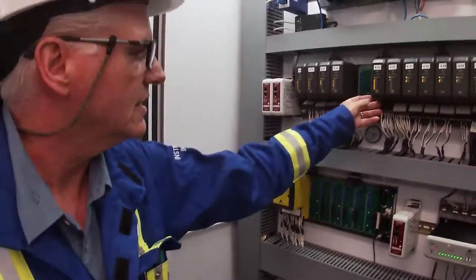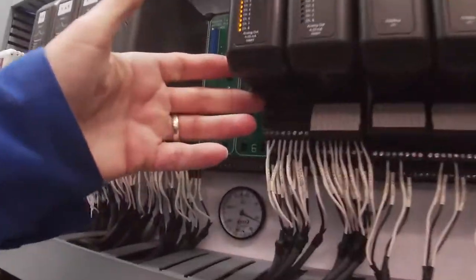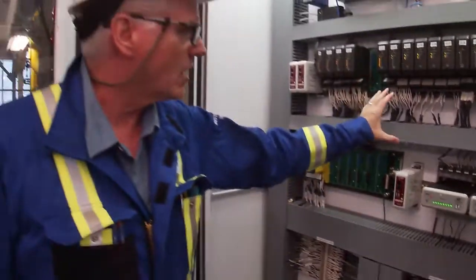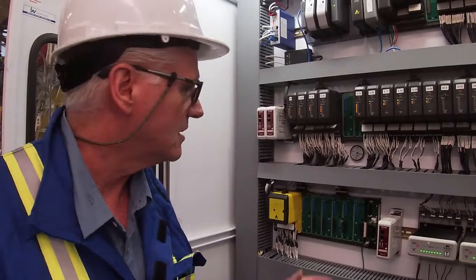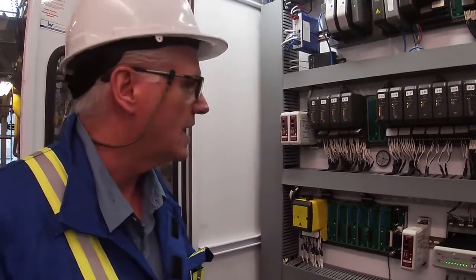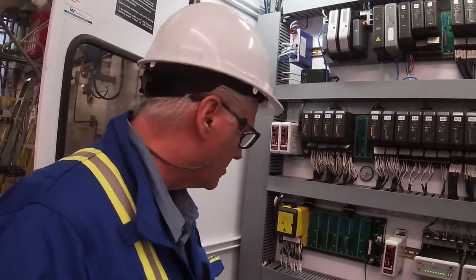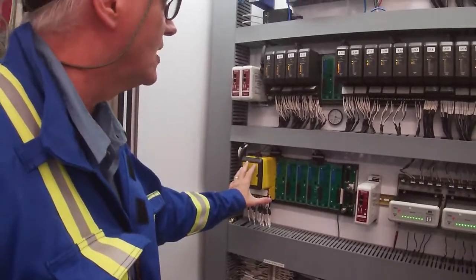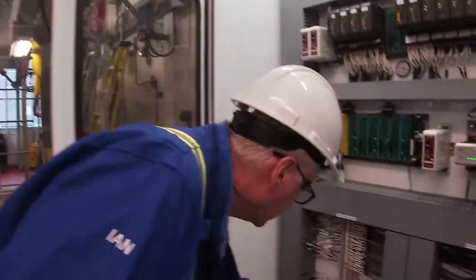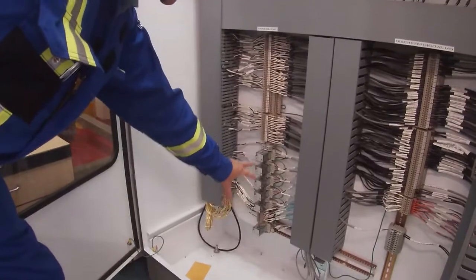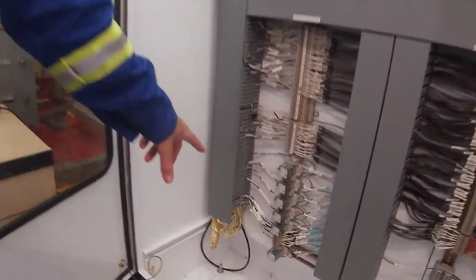It's the same thing here. If you look at any of our I/O cards here in our Delta V system, it's the same sort of scenario, and that's why we always like to take our wiring back down into a marshalling panel, so it's easy for the electricians in the field to pull their cables in without having to play around with I/O directly on the input cards or output cards. Anyway, so it's a universal module, different from the DCS where we have designated input cards, output cards, that sort of thing. And we wired down to a marshalling panel here, and you'll notice there's a bunch of relays here.